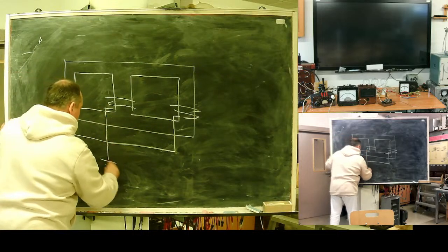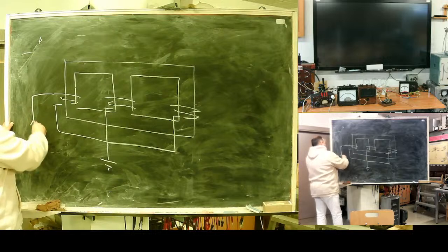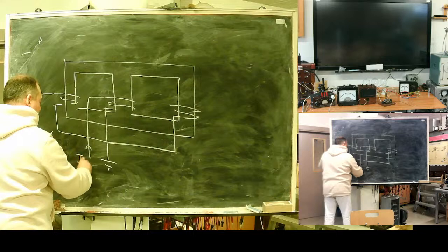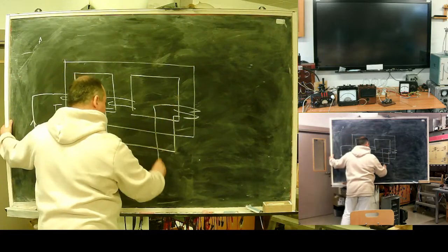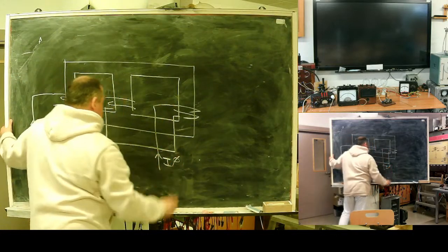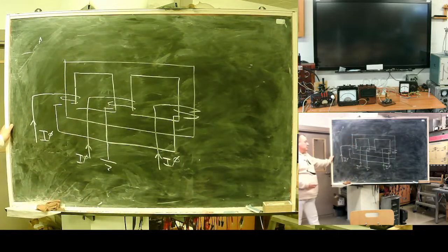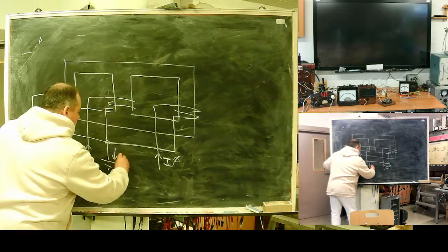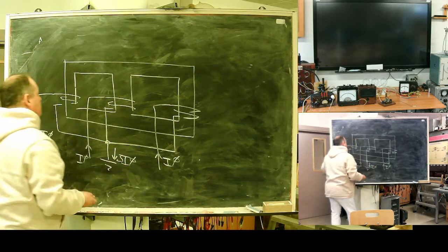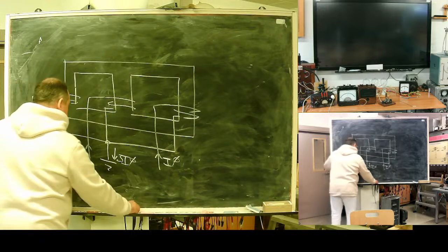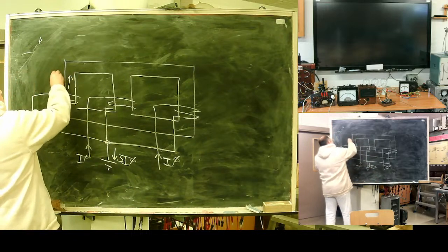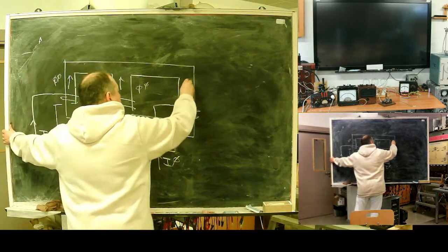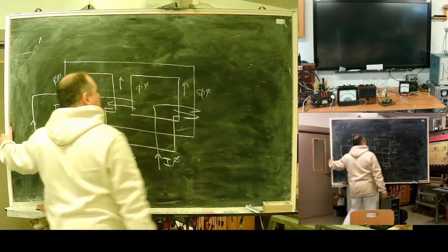I have a grounded network, and zero sequence currents flow into ground, triple I0. What will I see? Zero sequence flux, zero sequence flux and zero sequence flux.